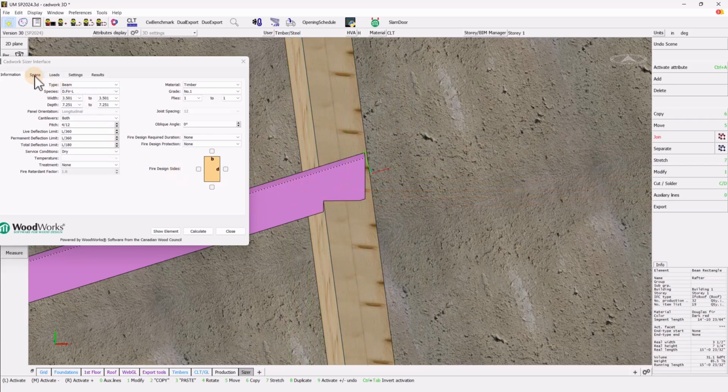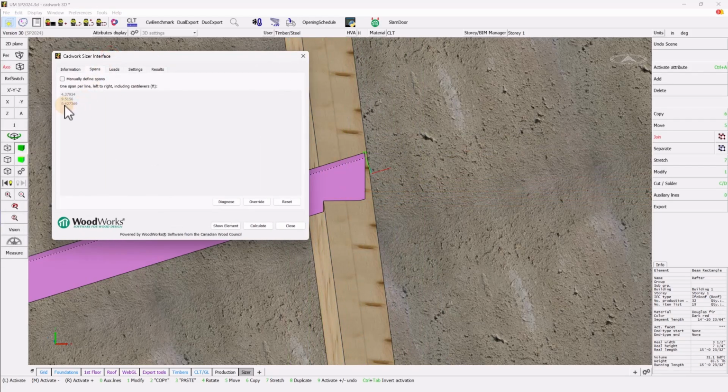A really small one, if I look at the span, we see that this is 0.4 of a foot, so not much. So I could either just leave it this way, or I could overwrite the span and change to let's say 10 feet. So I could check that and delete this here and change it to 10 feet.